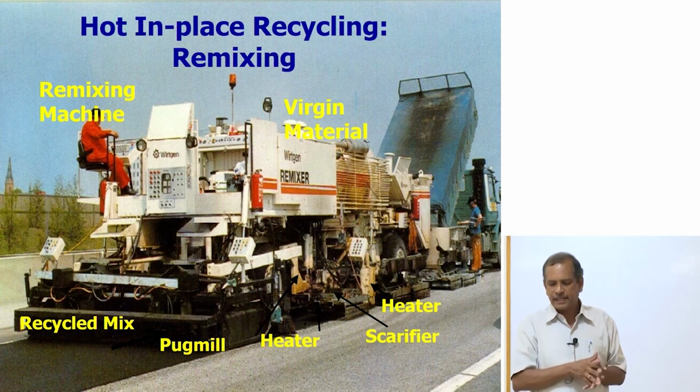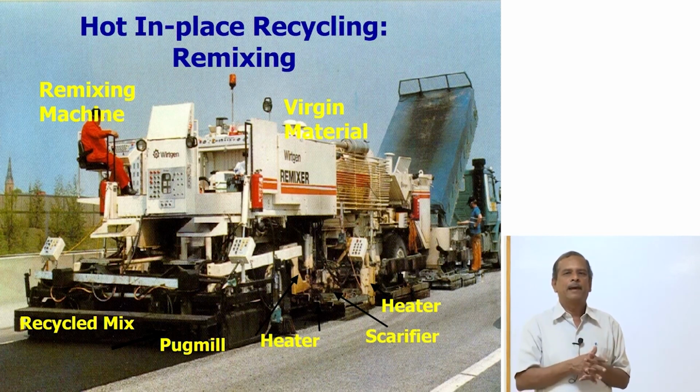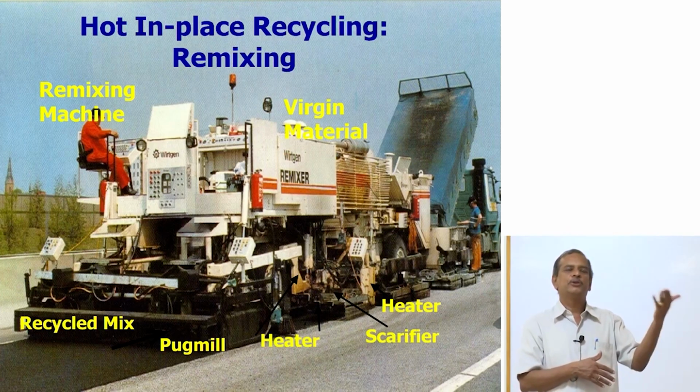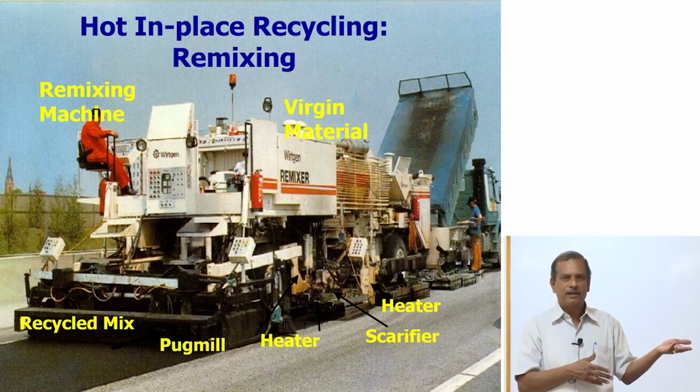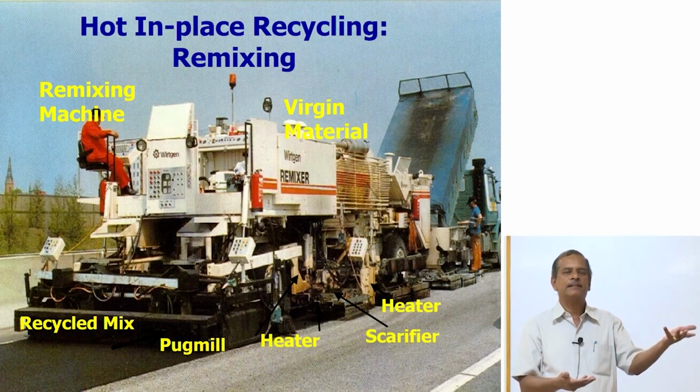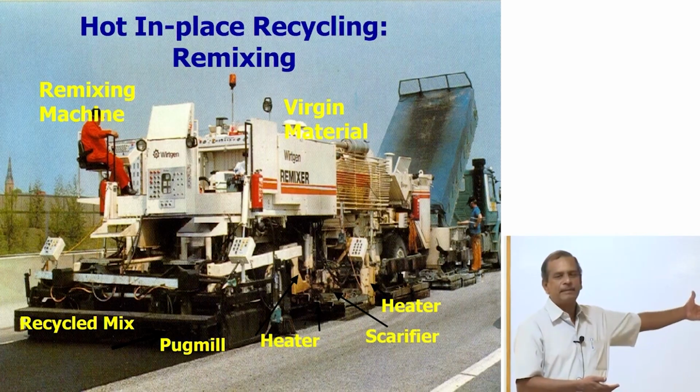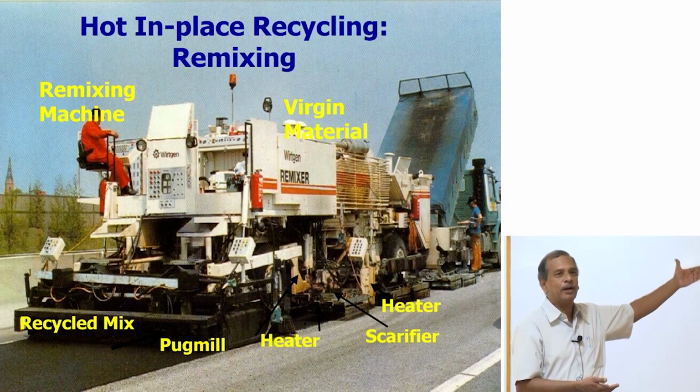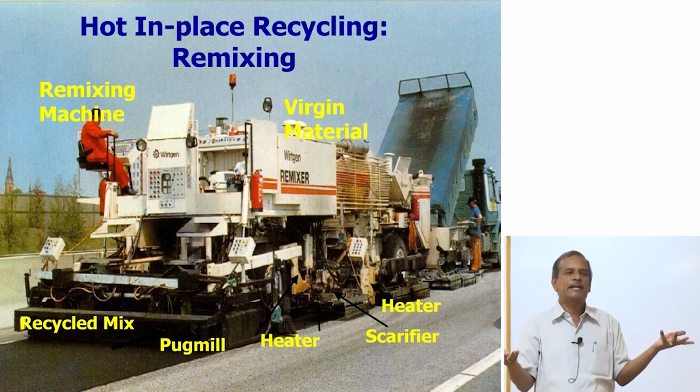So the technologies that have to be adopted in the years to come are, number one, you have to reduce the construction either by stabilizing the subgrade, using geocells, geogrids, geosynthetics, modified binders, or in the case of recycling, adopt white topping, or recycle the material, either hot recycling or cold recycling. Any of the technologies can be adopted.